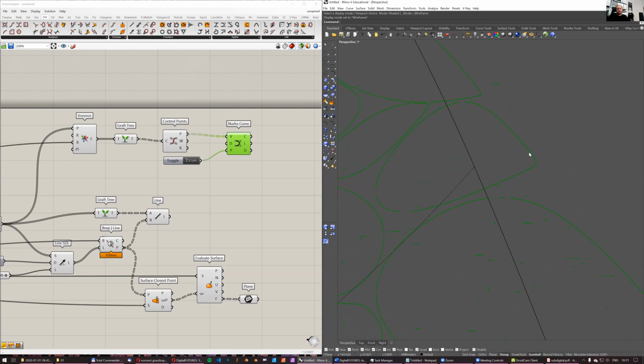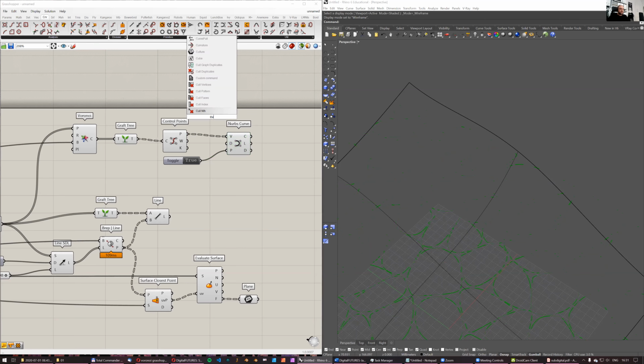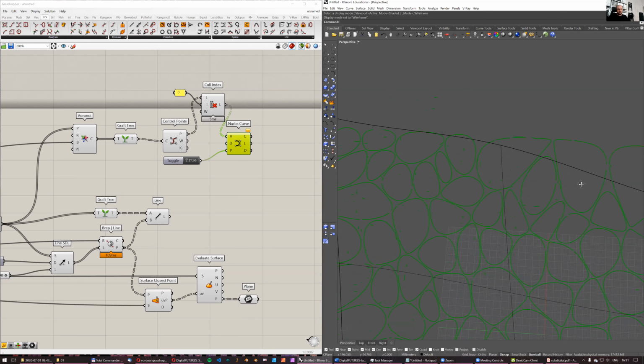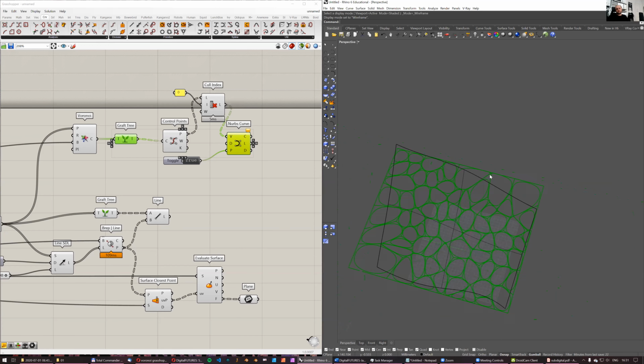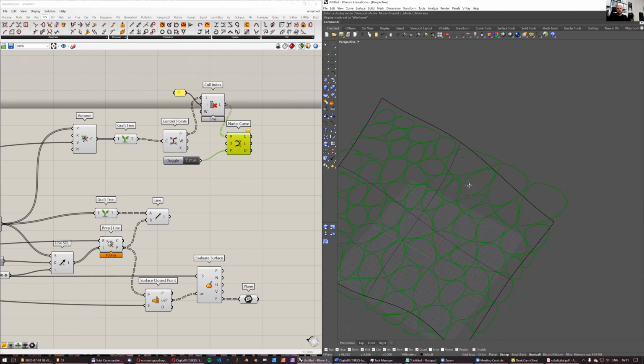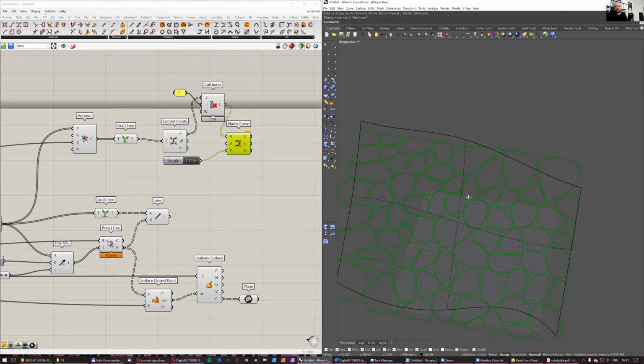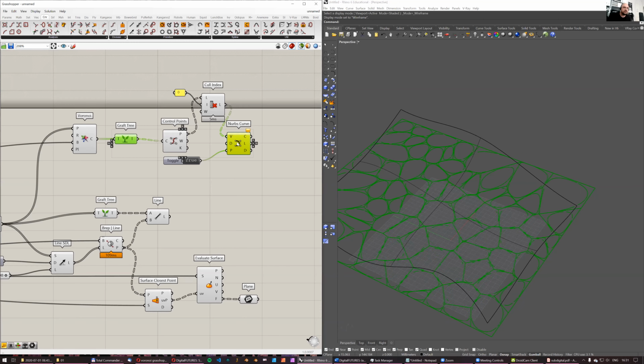Oh yeah, the reason this is so sharp is that this Voronoi cell starts here with a point, then goes here, here, here, and there is again the same point as the last point. So we can actually cull index, which means we are getting rid of the first point in the row because that one is there twice. And if I do this, it should work. And actually, it doesn't really look much better, but that's right. It doesn't look much better here because there are two points very close to each other. So of course, it doesn't look so good. But anyway, you see that I changed the original heart shape, this one, into something that is much smoother.